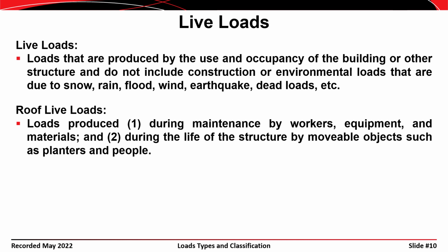Okay, roof live loads are handled a little bit differently in our designs. Roof live loads tend to be caused by maintenance workers or things like that. Maybe people checking on air handlers or HVAC units are on the roof, or maybe people washing windows and things of that nature. So roof live loads tend to be much smaller than live loads on the main floors or the main levels of buildings.